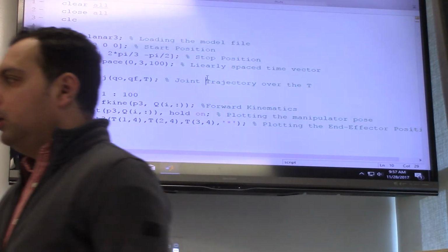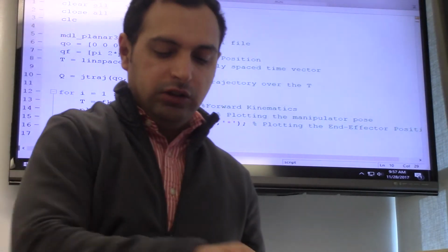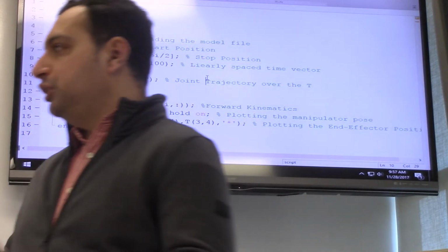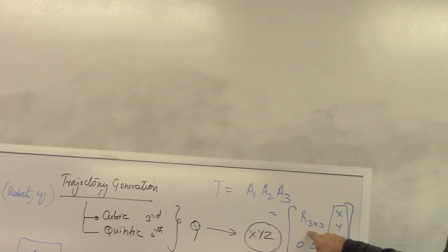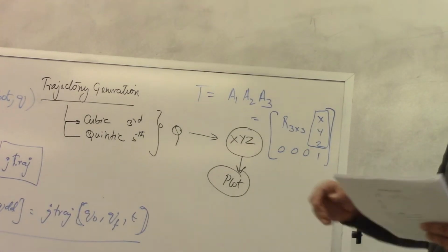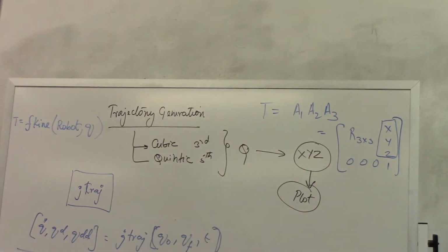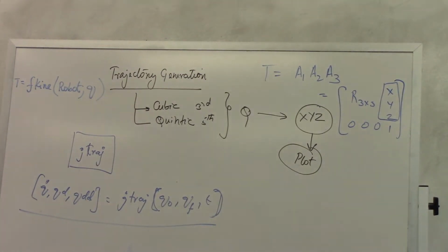Let's do one more thing. Let's load this. I'm going to give this out. We did the position. From this, we want to generate from the R matrix the Euler angles and the RPY angles. So let's do that. Let's pass this around. I'm going to do the first manipulator and I will require you to work with me to do the second one.